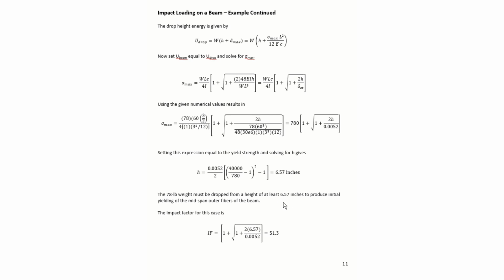I hope that brings into mind and helps you realize how critical drop height is and how significantly it can change the impact force and give you this impact factor that can be really high due to relatively small drop heights.